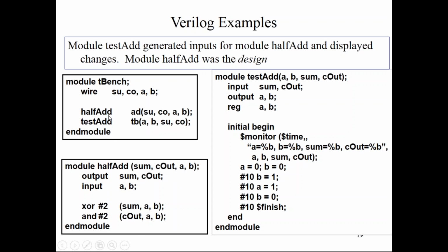So here I have to use the half adder module, and I'm using an instantiation name, and that name is AD. The same order we use in the module, we have to define the inputs and outputs here. For example, inside the half adder, if I'm using A and B as input first, and afterwards defining the output sum and carry, then I have to choose the same order here also. Okay.